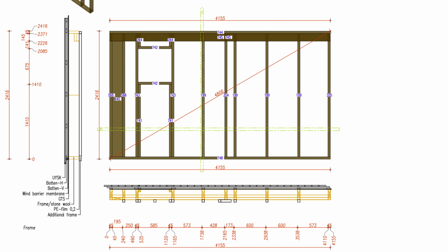Each element has three main measurements: the length, the width, and the diagonal. In several steps of frame assembly, it is crucial to check the diagonals of the element. During the assembly process, the diagonals might shift. Each producer has set specific tolerances for how much the shift is acceptable compared to the drawings. Usually, it is stated that the difference can be no more than ±1 millimeter.